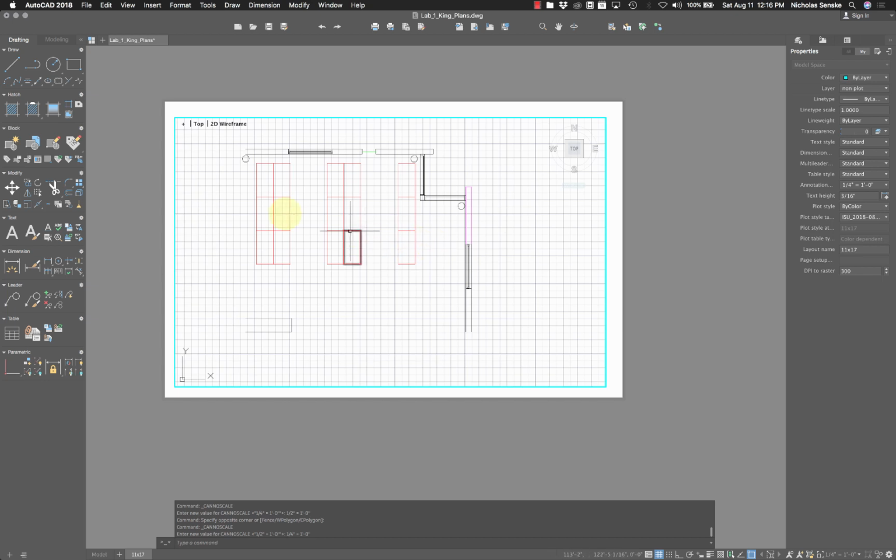So you'd say, well, how would I center the drawing? Well, one kind of trick that I would have is to say, if I make a square, and I would probably measure this better, but make a square, draw a diagonal across it, and then I can say zoom center, and the center is going to be the midpoint.